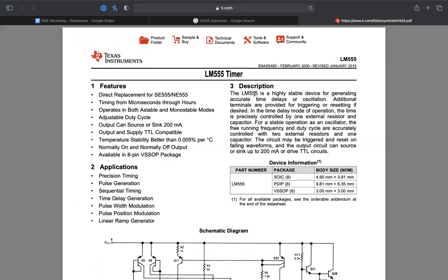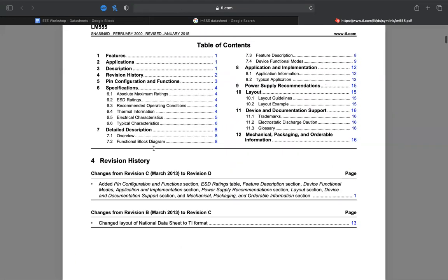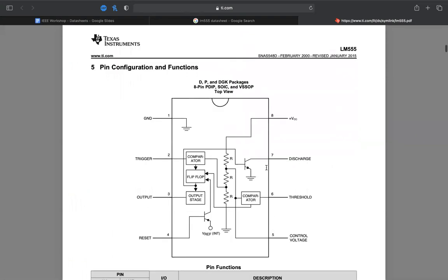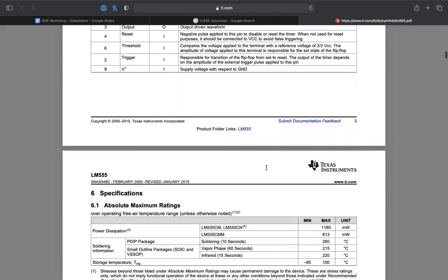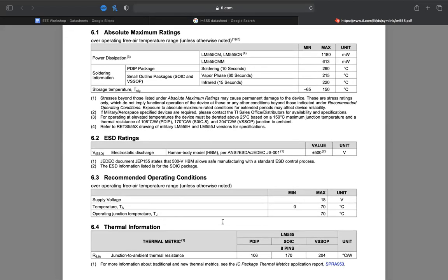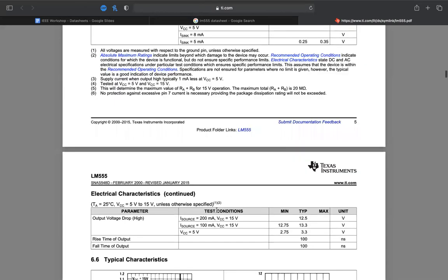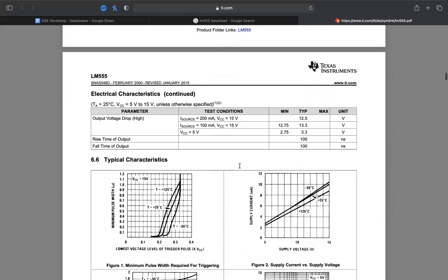And just like you saw earlier in the presentation, here we have our summary page. And then you might even get a table of contents sometimes. It varies, because your data sheet might be just 3 pages, or there are some data sheets that are super extensive and you have 100 pages worth of information that just goes on and on. But you can see you have your pin configurations here, like we mentioned before. You have your absolute max ratings, your recommended operating conditions, and